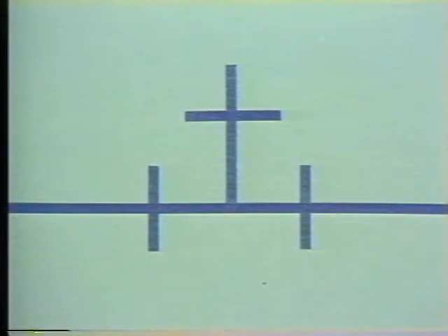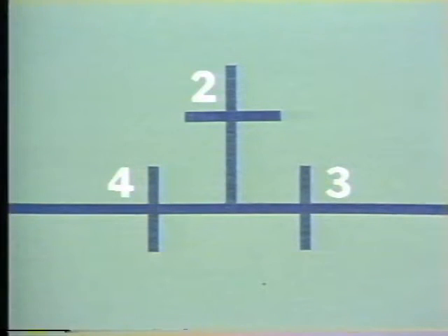This is a 4-inch by 3-inch by 2-inch T fitting. That means that the left pipe is a 4-inch pipe, the right pipe is a 3-inch pipe, and the branch pipe is a 2-inch pipe. If the main pipe did not change size here, the T would be described as a 4 by 4 by 2 T. The last number is always the branch connection.